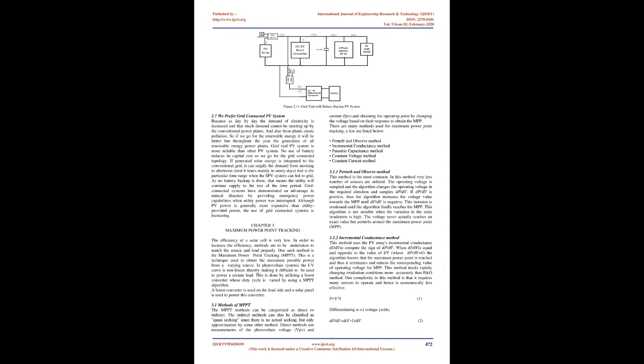2.1.3 Types of photovoltaic cells. There are essentially 2 types of PV technology, crystalline and thin film. Crystalline can again be broken down into 2 types. A. Monocrystalline cells, these are made using cells cut from a single cylindrical crystal of silicon. While monocrystalline cells offer the highest efficiency, approximately 18% conversion of incident sunlight, their complex manufacturing process makes them slightly more expensive. B. Polycrystalline cells, these are made by cutting microfine wafers from ingots of molten and recrystallized silicon. Polycrystalline cells are cheaper to produce, but there is a slight compromise on efficiency, approximately 14% conversion of incident sunlight.